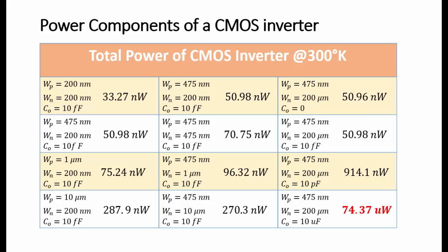If we are interested in lowering the power of our CMOS inverter, we can simply adjust these parameters so we can get the total power as we want. But we have to change them carefully, as we saw before that the width of both NMOS and PMOS affects directly the symmetry of the VTC, which has great impact on other properties that we will talk about later.